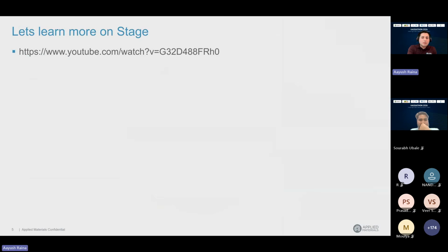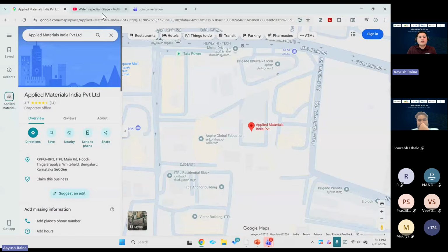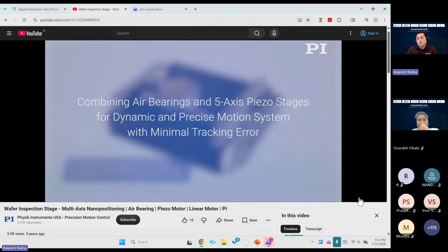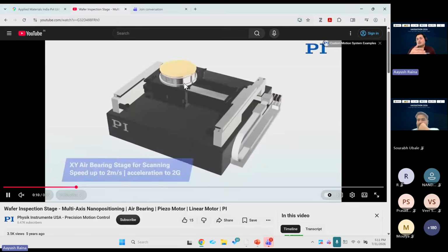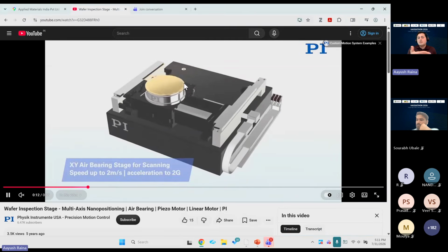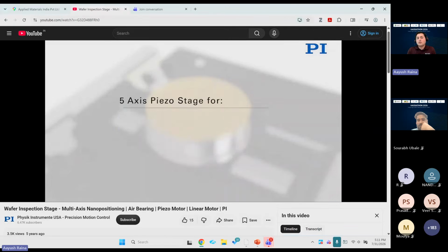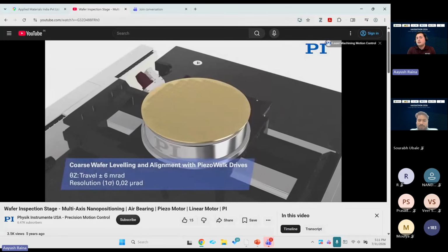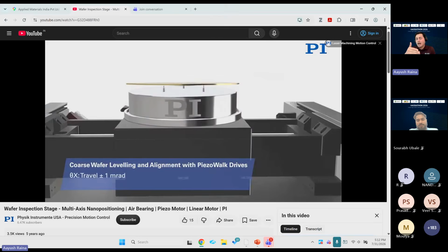So now let's see why this error comes. We'll spend at least a minute to understand why it is happening. Generally, these wafers are kept on such stages. If you see, these stages are moving and the microscope is fixed. Since your stage is moving on motors, you may have some errors in the stage movement due to vibrations and angles.